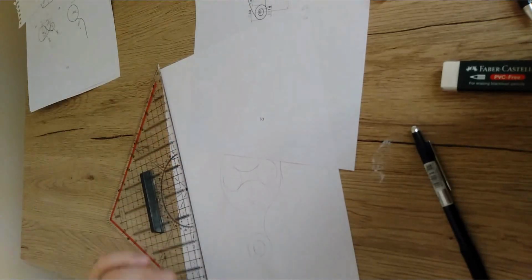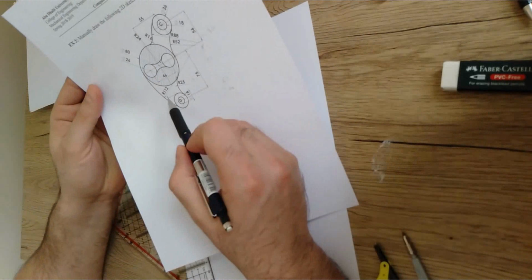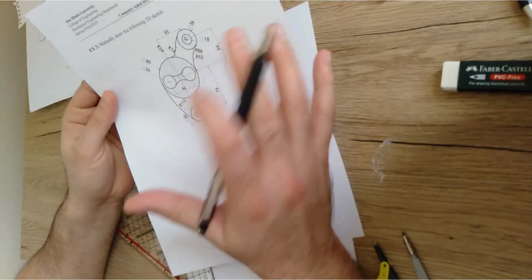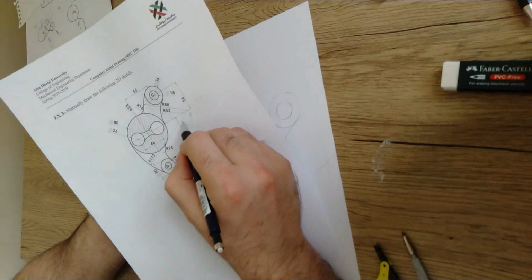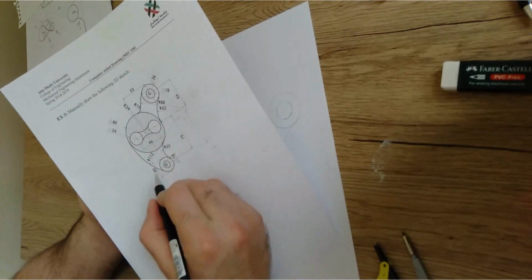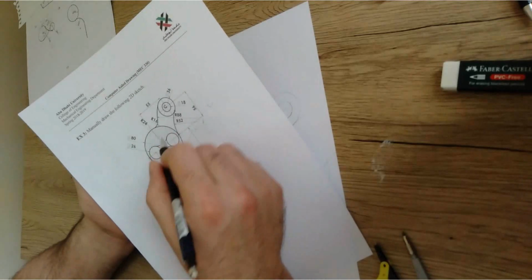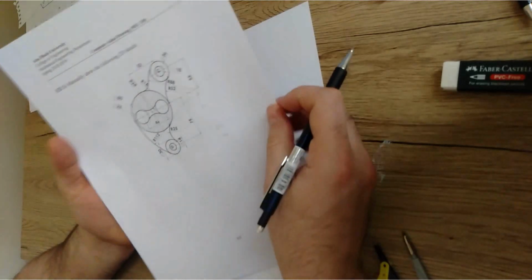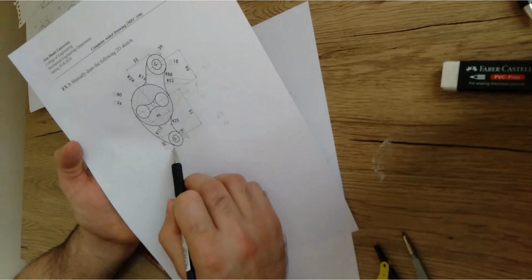How about the other curve, 112? It's going to be the same, but where should be the location, or a tentative location, of the center point of this big curve? It should be somewhere on the right here, right? So, what are the tangent points? It has two tangent points. One point is tangent to the big circle, so I'm going to use the center of the big circle, and there is another tangent point to the small circle here with diameter 13.